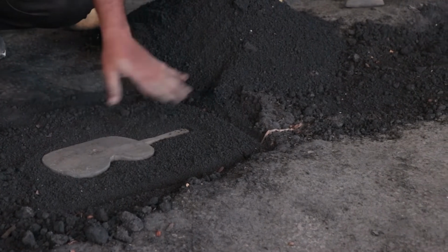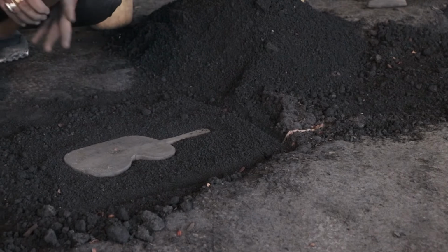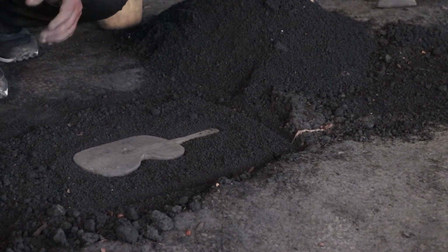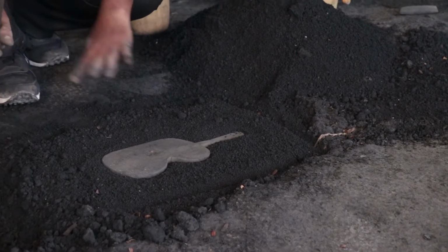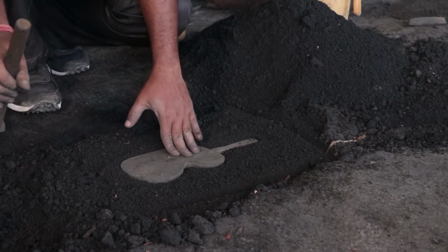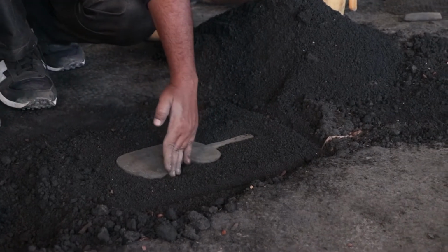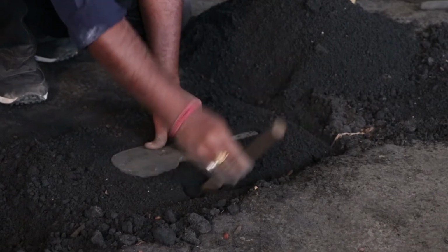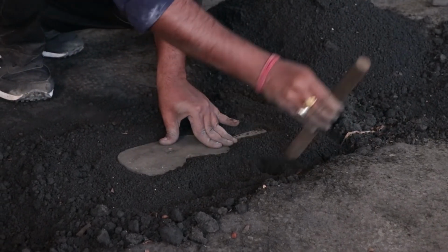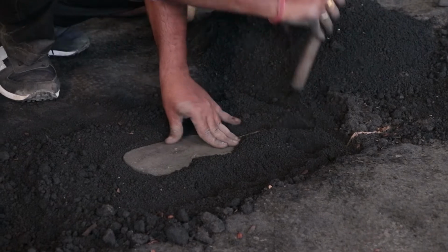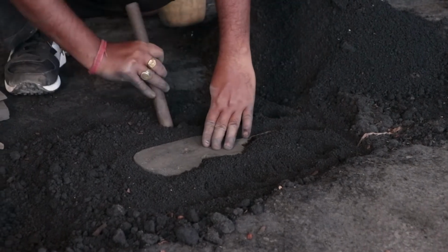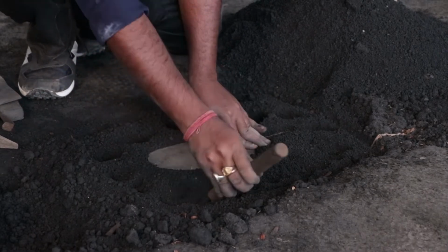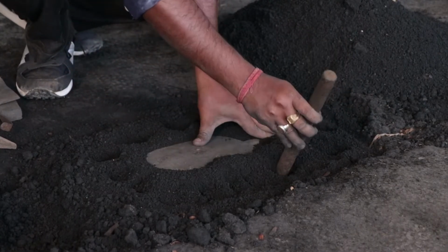Once this pattern is penetrated in the green sand, you will need this. This is basically known as rammer, as it has been already explained to you all. With the help of this rammer, we should ram the entire portion which will be towards the pattern. This is the pattern, so we need to catch it in a horizontal way and we need to ram it towards the pattern. While ramming towards the pattern, make each and every sand particle enter the core and the hollow places of the pattern.